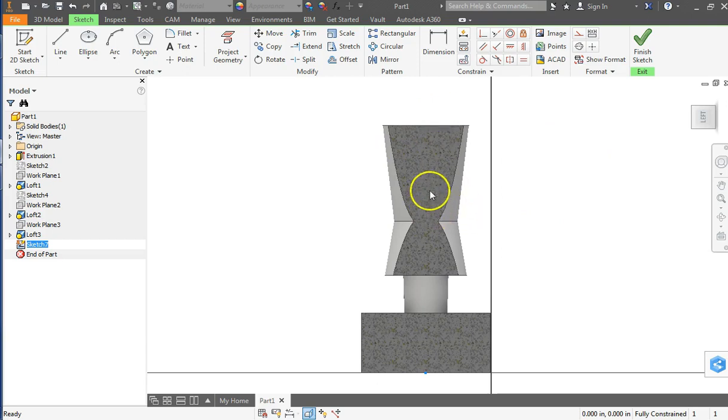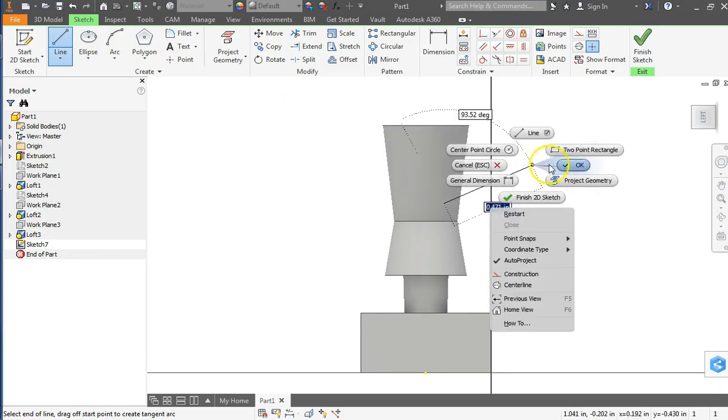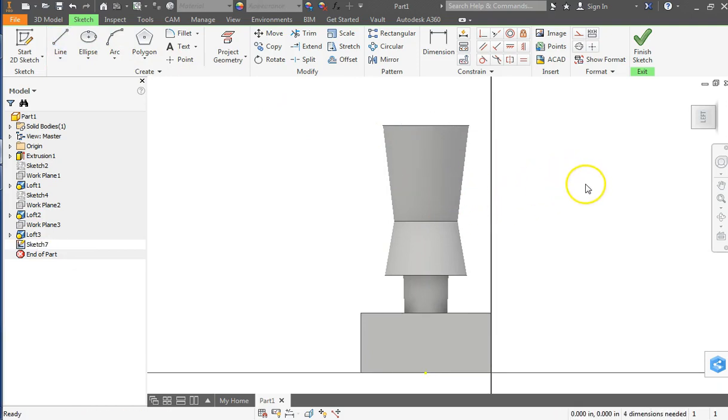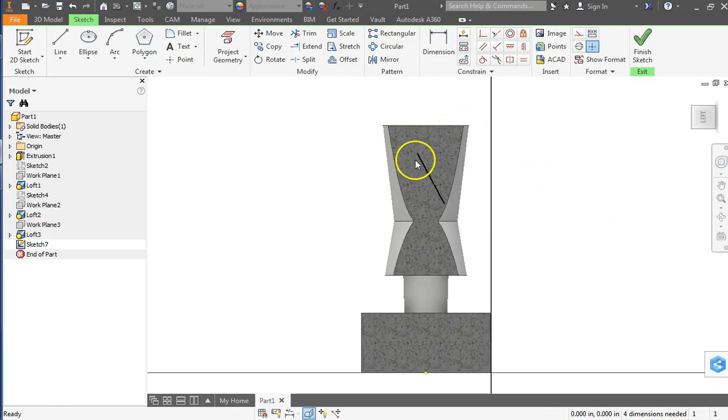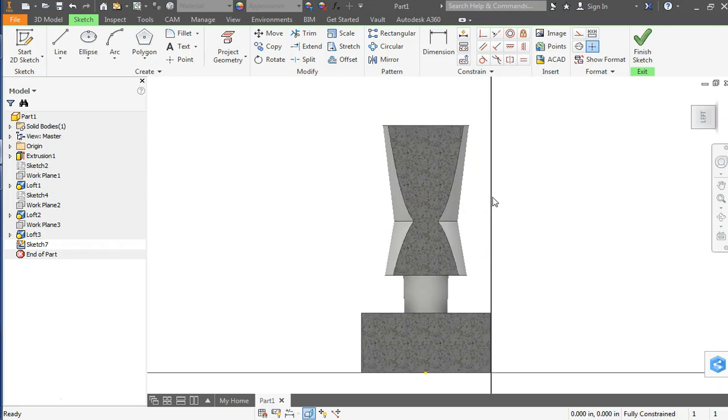It's really nice because if you are sketching within this area, it gets all the material that's in the foreground in front of the plane out of your way so that you can see your sketch lines. Otherwise, your sketch lines are literally inside the workpiece and you can't see them very well. So if I made a sketch right here, for example, I can't see that line usually. If it's not highlighted, I can't see it. But if I hit F7, then I can see down to that plane. So it is there, and it is something you can select. You just have to know where it is, and sometimes it's hard to find it.